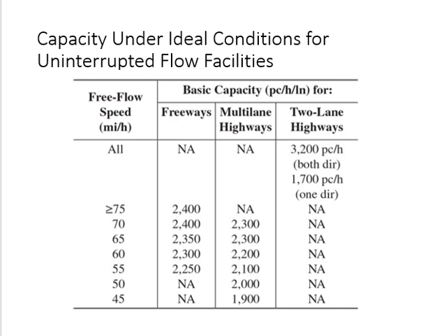This is why they are not the same. This is the effect of 1 lane over the other. In 2-lane highways, because there is only 1 lane in one direction, that lane affects the other direction as well. So the direction which has more volume affects the other direction as well, even if it has a gap. So due to that effect, both lanes cannot go up to the same value, never. One will always be lower. Okay? Clear? Sarah?